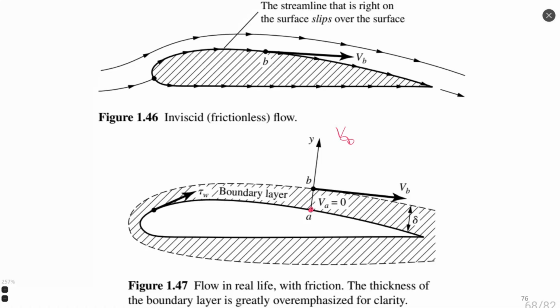Boundary layer is also characterized by its thickness, delta, as we may see here. This thickness tells us where the velocity stops changing due to the influence of viscosity forces. If we draw a profile of velocity, for example, like this, we will see that this thickness here is a point where velocity does not change anymore. This is the profile of velocity I draw.